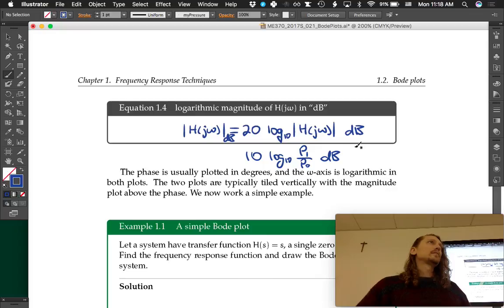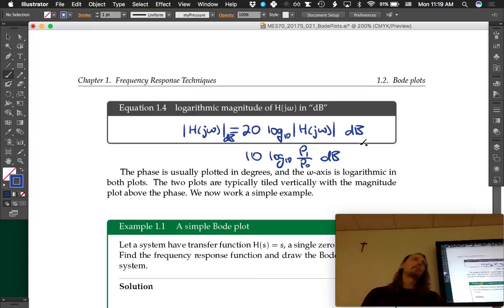I think we learned it in intensity. In physics? Yeah. But we learned this 10 log of I over I naught, where I naught is your smallest decibel that can be heard. Yeah. So when you're talking about sound waves, you're talking about power, so they use the power one. So it does depend. In electrical signals, you can use either the power one or the magnitude one or the amplitude one.